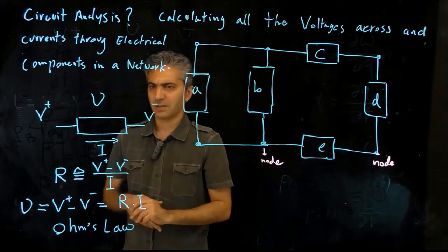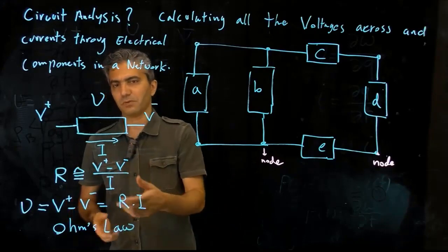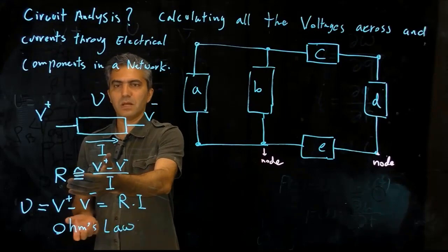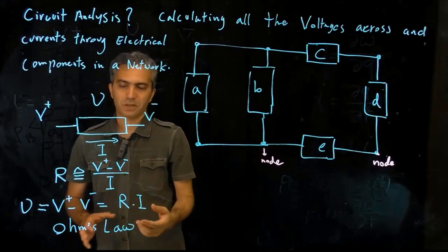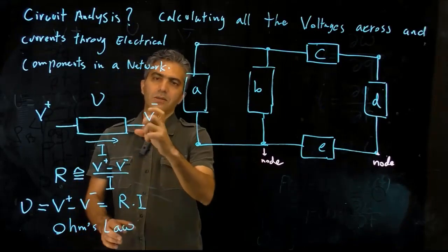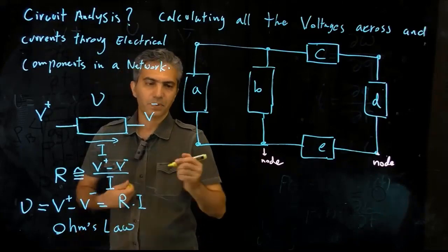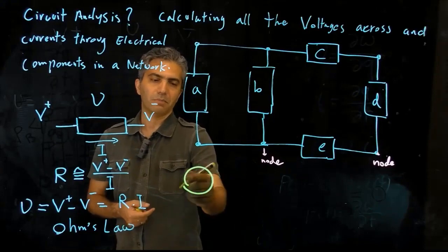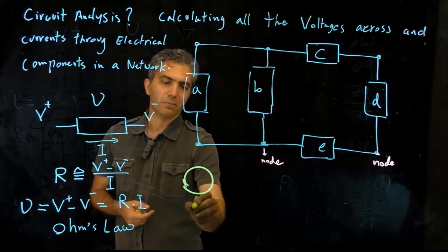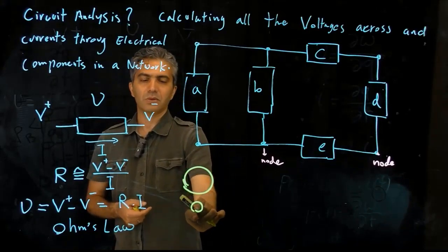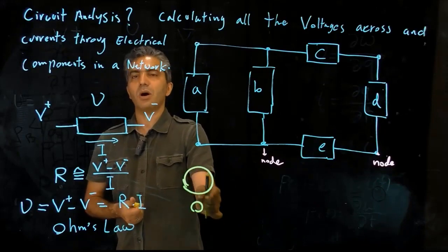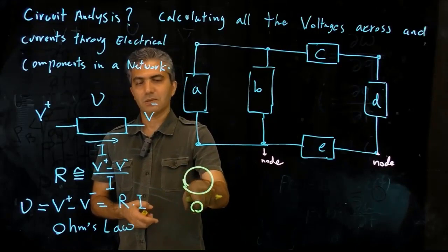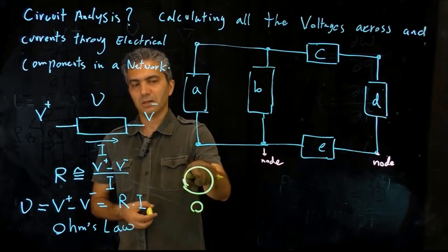And we can quickly discuss how that is. For example, most likely a lot of metals have low resistance, but in the same metal, for example, if you take a certain cross-section of the copper wire that you use, and then you compare that to this smaller cross-section of the same copper material, the resistance that you get out of this is more than the resistance that you get out of this.